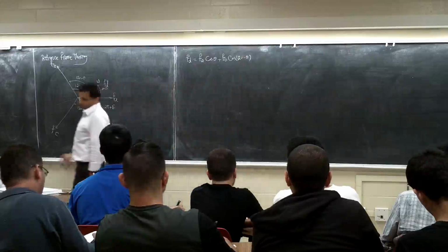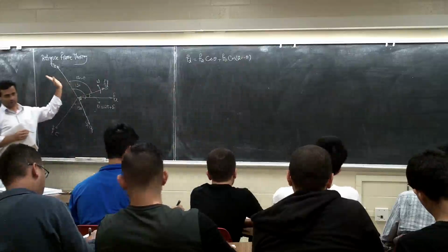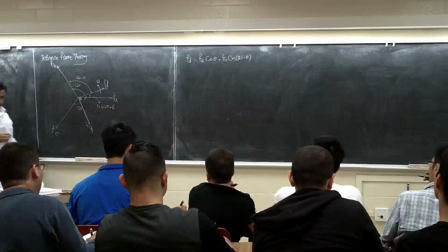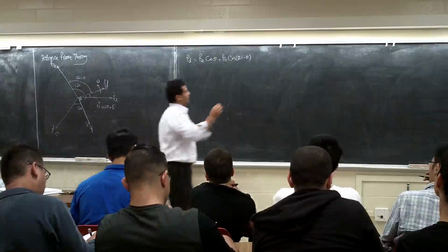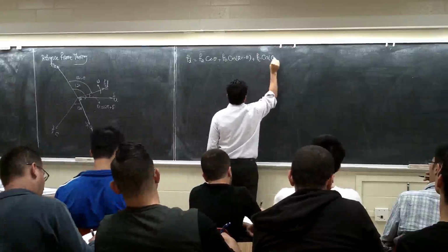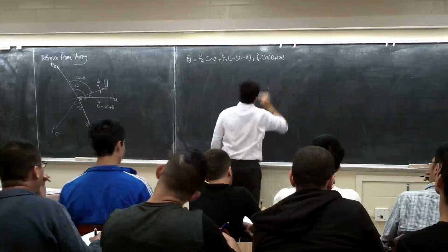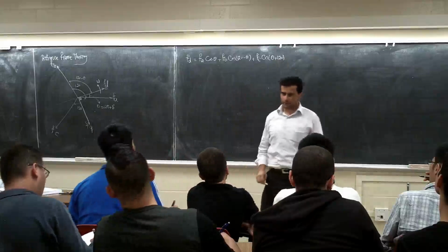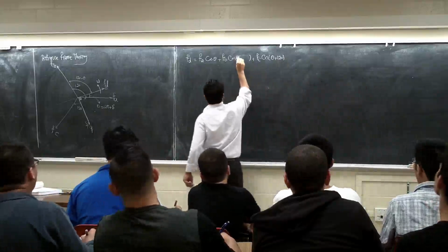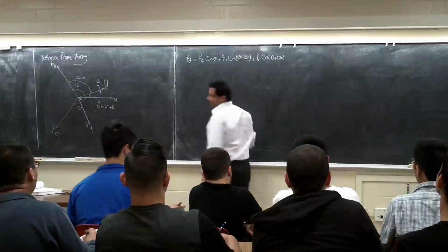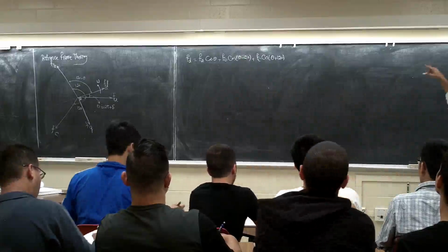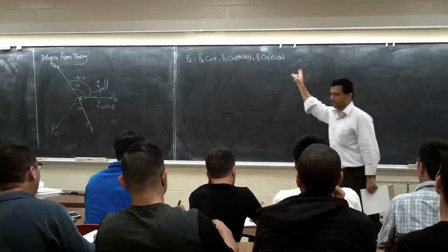Cosine of this angle, right? That's a projection. Whatever is this angle times cosine of that angle. How about the FC? The angle I'm playing to be of 120, right? I'm going to change this one to this one. Instead of 120 minus theta, I made it theta minus 120, because I want it to be like a three-phase system: 0, minus 120, and 120.